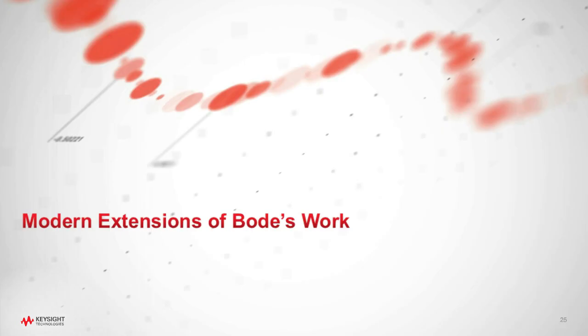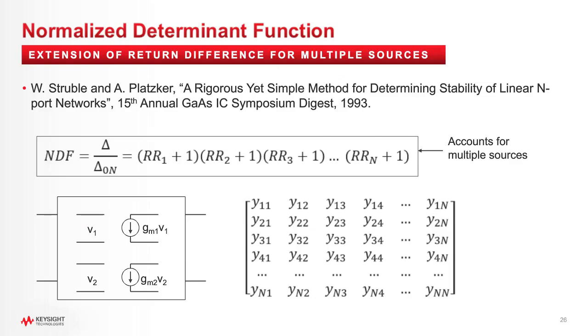Okay, I'm going to move on now to some modern extensions of Bode's work. So Bode's work was done in the 1940s. It's based on like one vacuum tube, right? So today, if you have a circuit, usually you've got multiple active sources. In fact, you probably have multiple transistor models, and multiple transistors in a modern circuit. So Wayne Struble and Ariel Platzker came up with this extension of Bode's original return ratio concept to allow it to account for multiple sources.